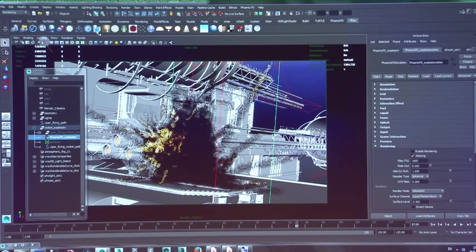I can use a new feature in V-Ray 3.0, which is called V-Ray Volume Grid, which allows you to open up the OpenVDB standard for volumes and simulations, which can be brought from external software. It's an open standard, and it also supports Phoenix. However, in its current state, it doesn't show you a GPU preview in the viewport. So this is why I used the Phoenix container, or the Phoenix plugin here, so that you can see that in the viewport.